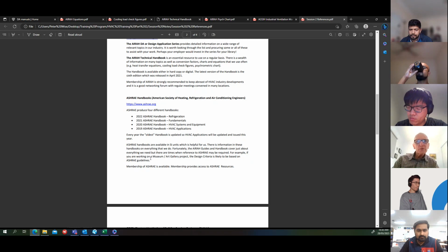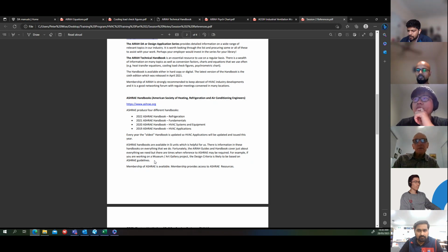For example, if you're working on a museum or an art gallery project or an archive store or something like that, design criteria may be based on ASHRAE guidelines. And I've done one of these not that long ago in Sydney, when was it, 2018. We did a museum at University of Sydney, and the design criteria was based on the ASHRAE standard for museums and art galleries, and they give them a rating of A or AA.